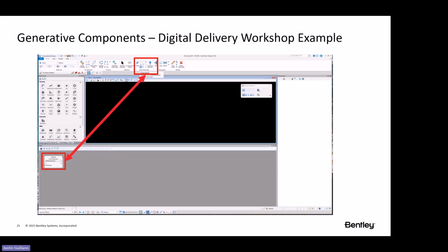So if you're using that workflow, it's always the best practice to bring in your offset coordinate system relative to basically the center of your project location, depending on how big it is. If it's a small section and you're only building in a certain area, you can refine it down and have it more specific. But generally speaking, you want to take that rough XY of the middle of your project and use that as your negative values for your offset coordinate system.